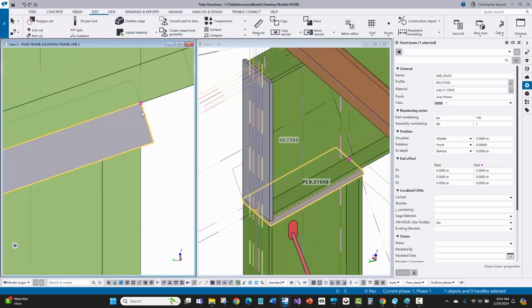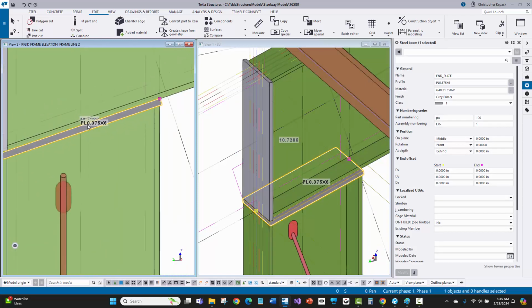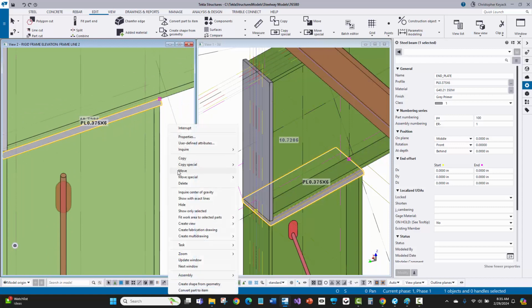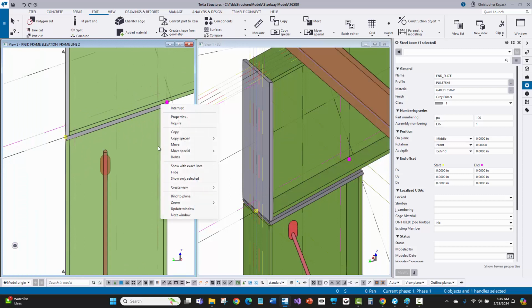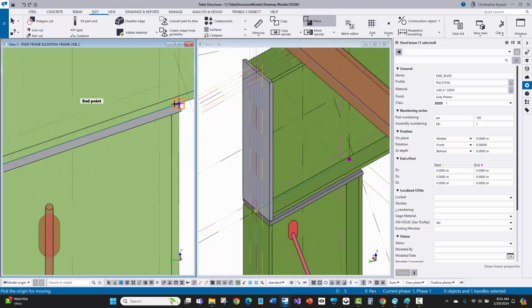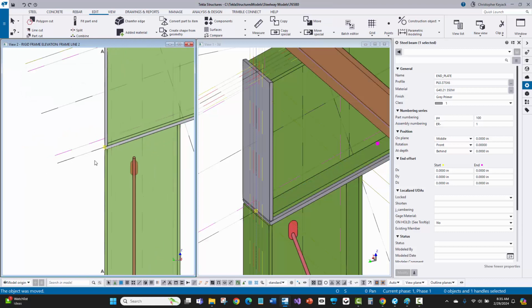Now, what I might do is I might actually stretch this a little bit further. So, right now it's 10 3/4-ish. So let's actually just stretch the end of that plate. So I'll just grab that point there, and I'll just move it from there. So I'm going to pick that point as the origin. When I do this, I'm going to say Control left click and just go ahead and type in 14.0. And let's just see what that gives us.